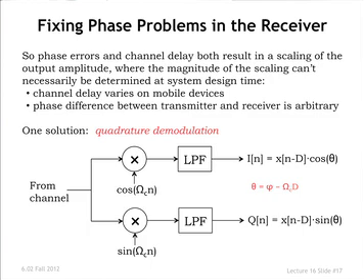If you go completely bad on one channel because you got the phase completely wrong with the cosine, you're going to do all right on the sine channel. If you do completely bad on the sine channel because you got the phase wrong, then you're going to do all right on the cosine channel. So at least one of them will work, and more typically, both of them will work a little bit. And what you'll then do is combine the two outputs.